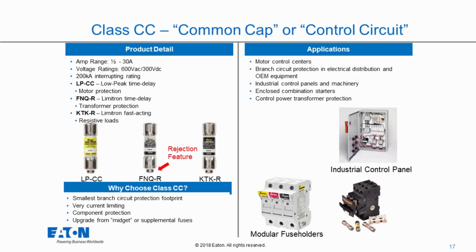It's hard to tell on your screen, but this fuse is only 1.5 inches long, right? So it's a very short fuse. It's only maybe 0.4 inches in diameter, so it's a very, very tiny fuse. And this fuse can safely interrupt 200,000 amps, which is pretty incredible.